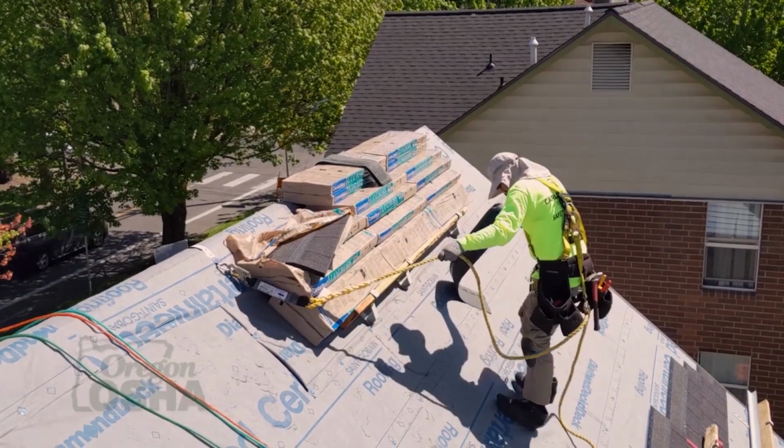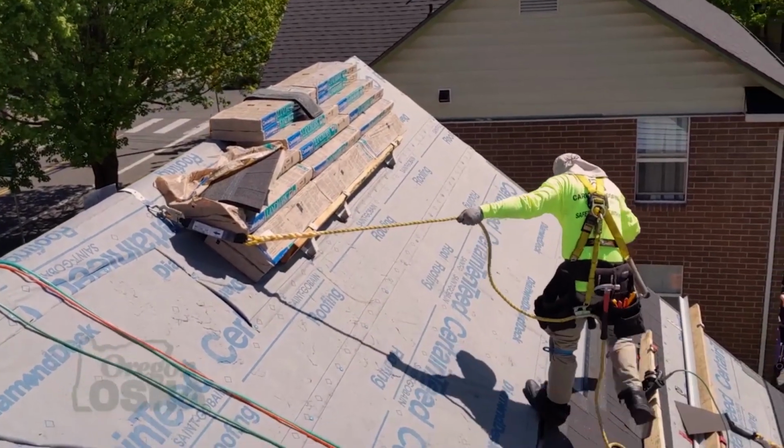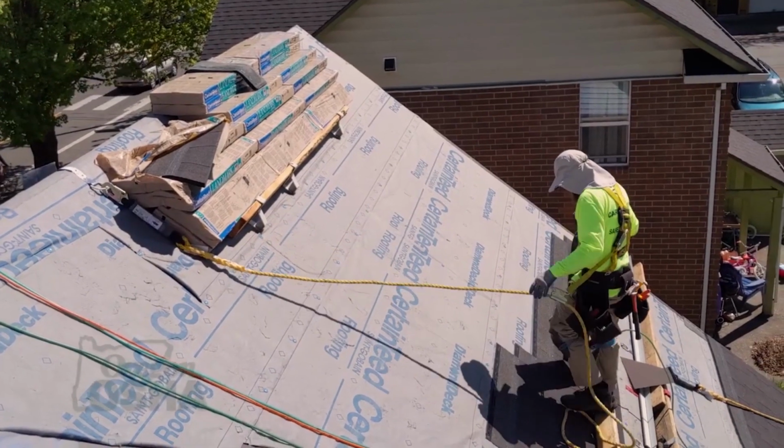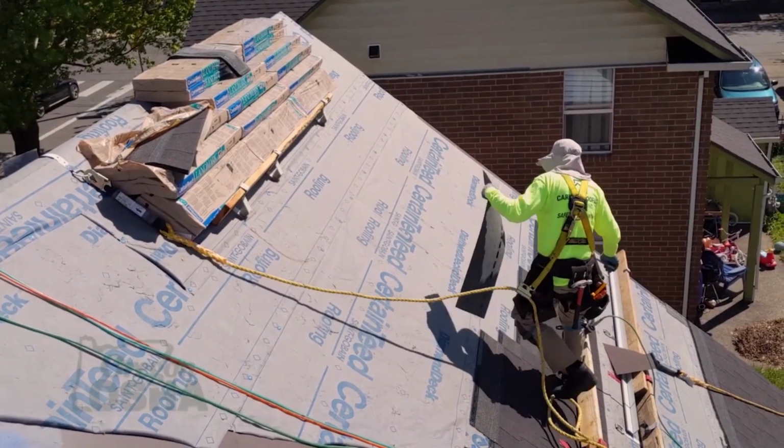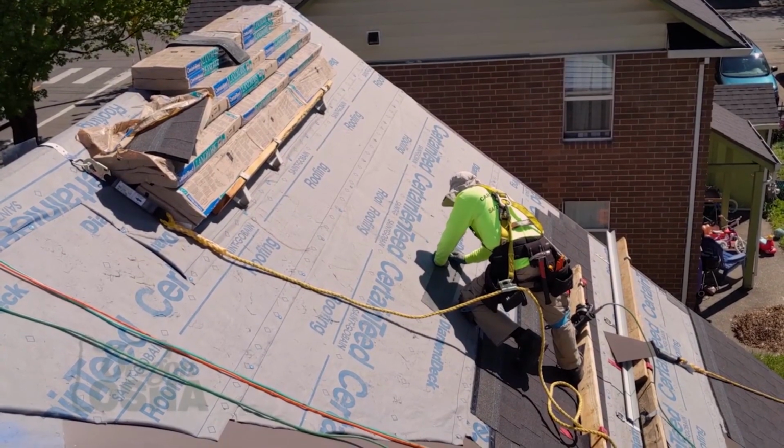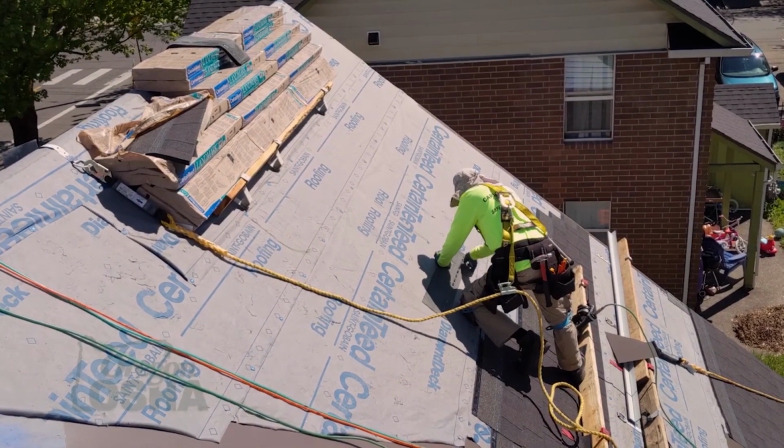You have to accommodate for your lanyard, for the shock absorber, and then the rope you have behind you for your fall protection. You have to make sure that the foreman is watching his crew to make sure that they are keeping their ropes tight, so that they don't have so much excess that if they fall off the roof that is 10 feet high, by the time you hit your shock absorber, then your 3 feet that you're going to extend anyways, you're going to hit the ground before anything works. So you have to make sure that you are taking into account your fall restraint, your fall arrest, to make sure that you're measuring that properly so the crews can be set up safely.